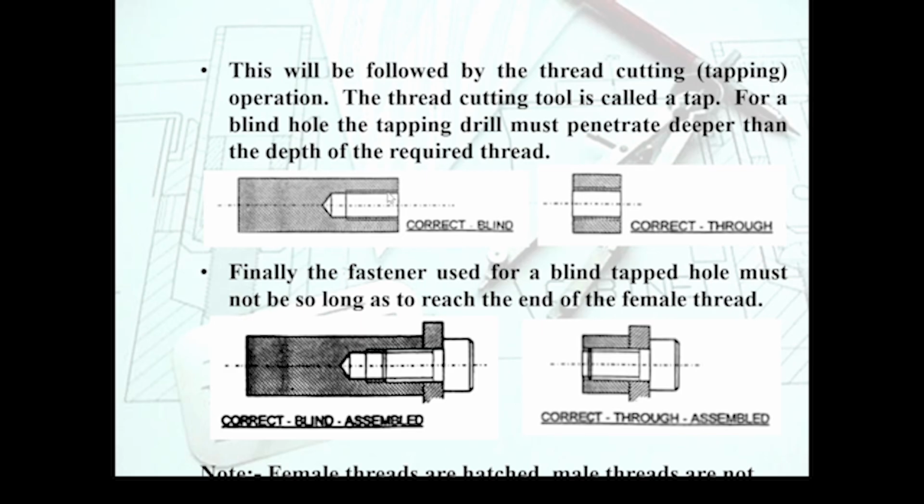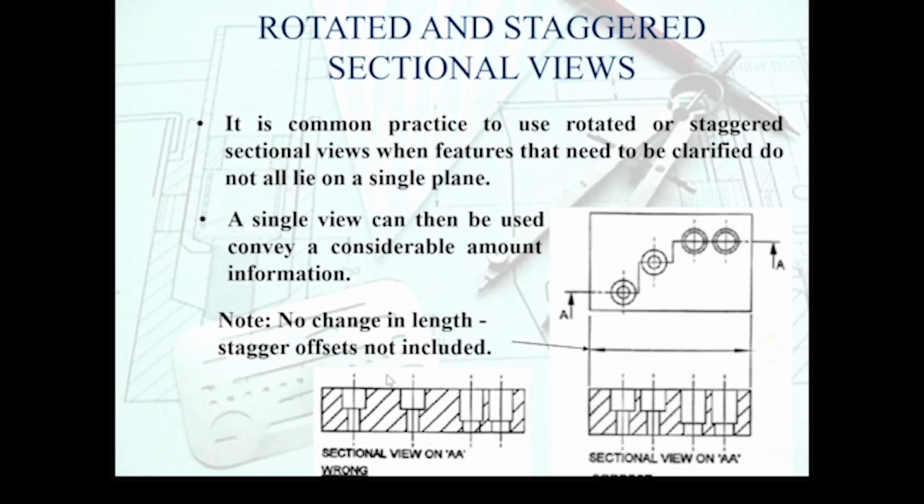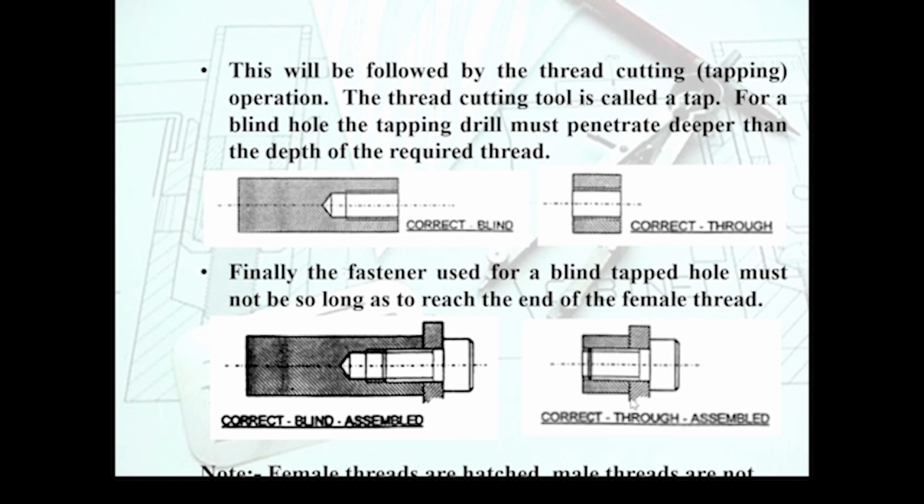Something very similar in terms of sectioning the shafts through the hole. You have to bear in mind that standard components like a cylindrical shaft, once again, fall in the category of a spindle. They do not need to be hatched in. However, the rest of the material around it can be hatched in. Once again, the shafts can be threaded, and we need to indicate the presence of threads on the shaft by a continuous thin line, as you can see in this particular drawing.